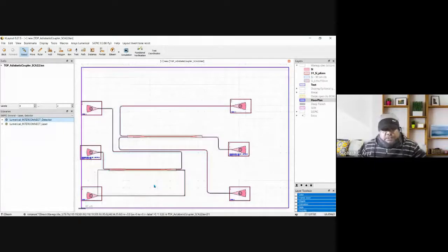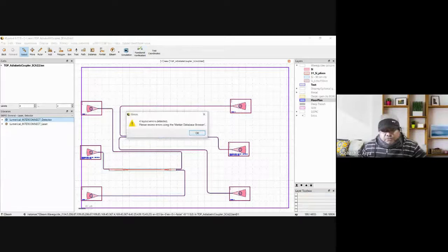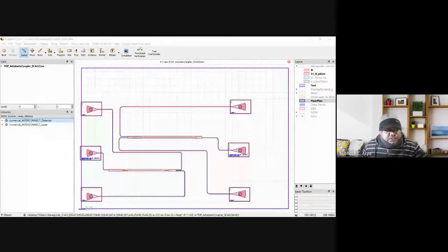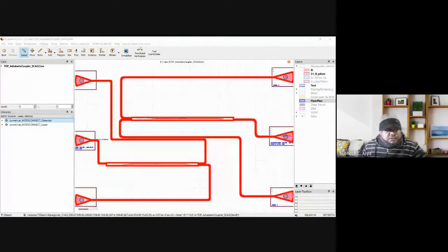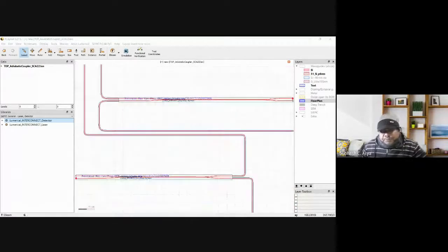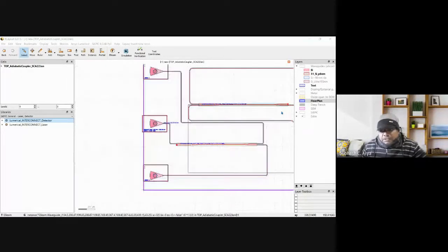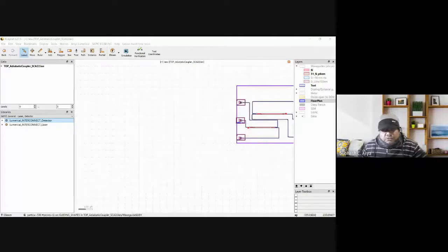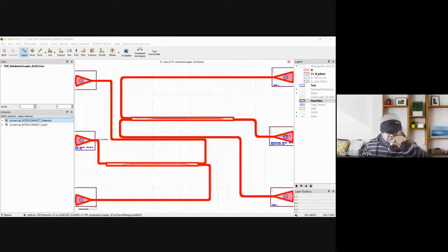I hope everything is fine. Let us go for functional verification. So core layout error, what are those? Let us see. I think this is related to a disconnected pin. Yeah, it is a disconnected pin. Okay, one pin is not connected. Yeah, here that is and here. So we can put a terminator on these two and these two pins, and others are this.